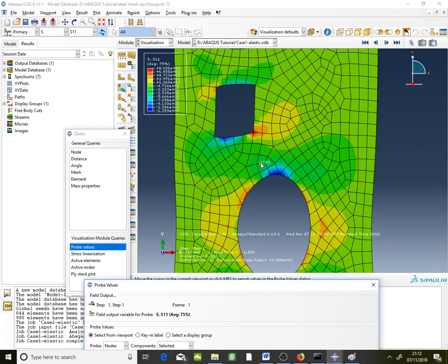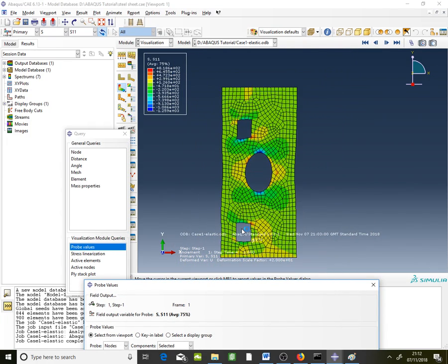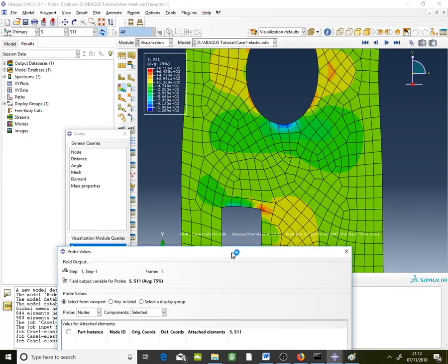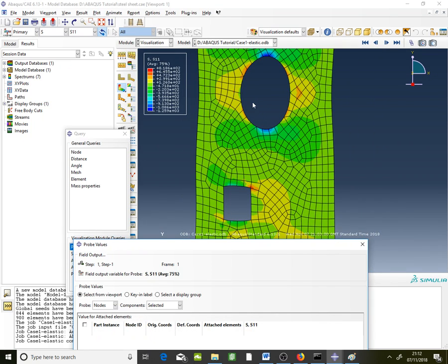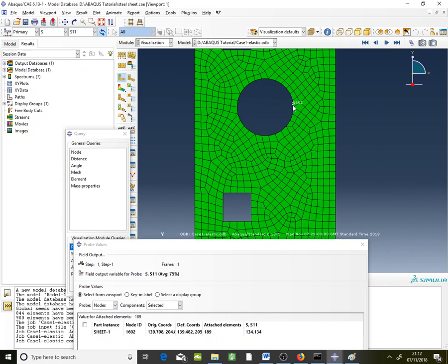Now you go to your last one here, and you click here, and you have 685.64, and for the circle, let's undeform it, and then we can move around here, at 84.3, and here, which is minus 1259.3. Negative means compression, positive is tension.